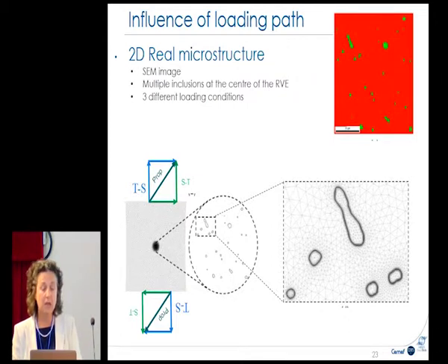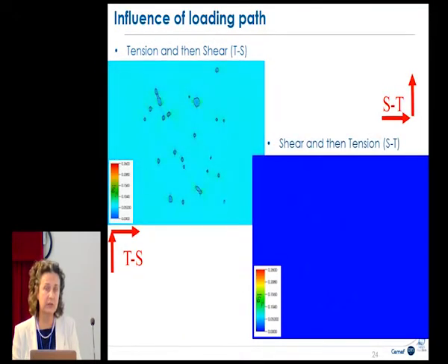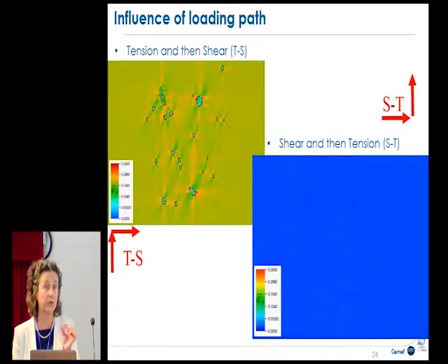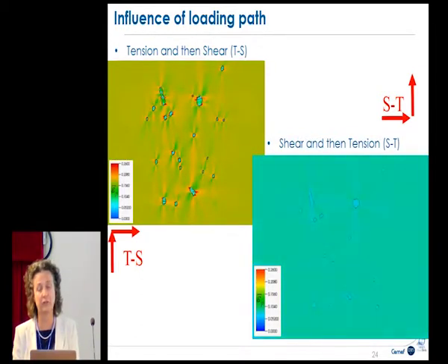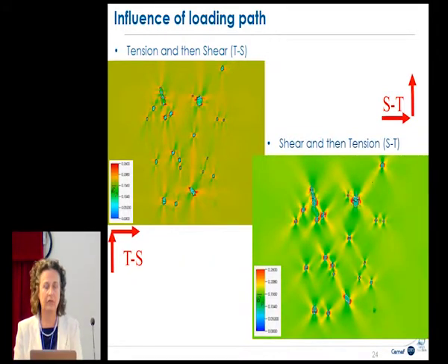In this case, we try to minimize the dimension of this zone, and we have to change and evolve the mesh in order to decrease the thickness of the interface to have a very, very small thickness here. It's like a body-fitting mesh adaptation. This is also a possibility.